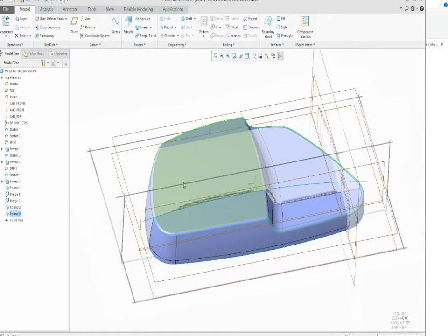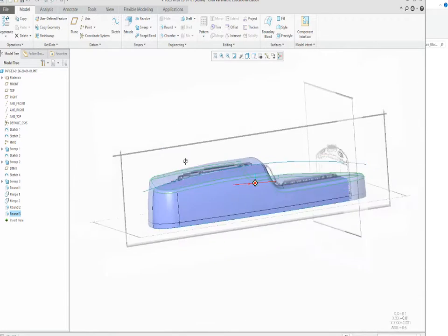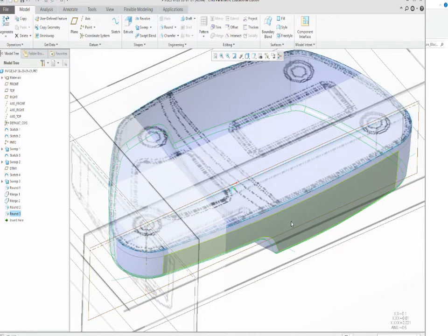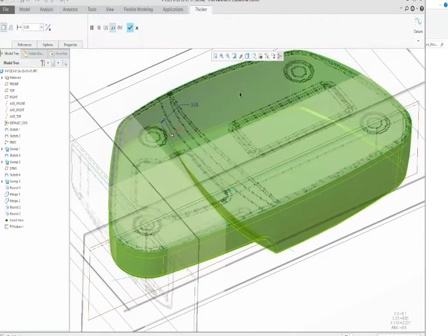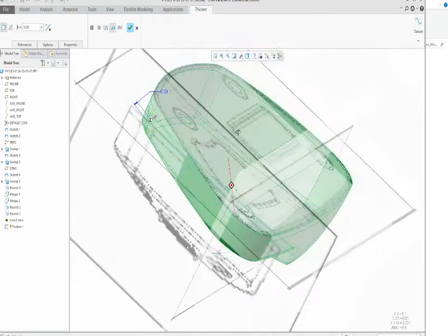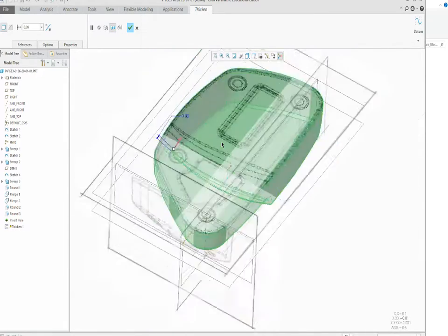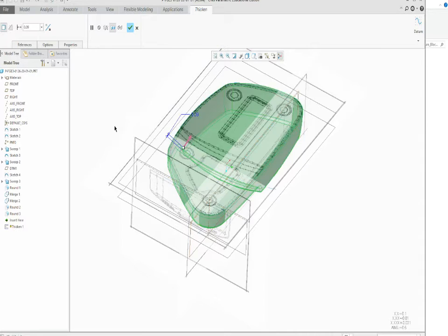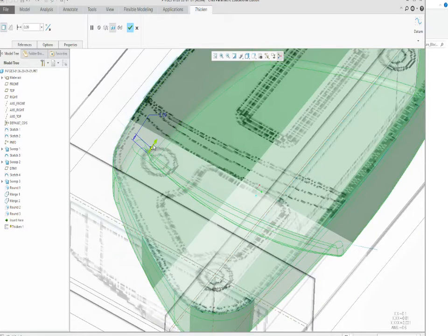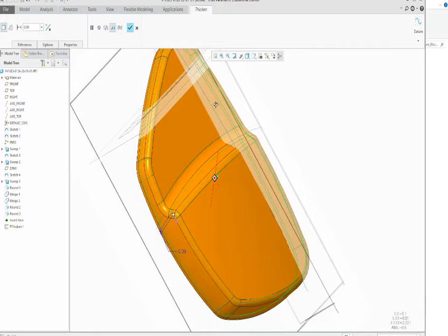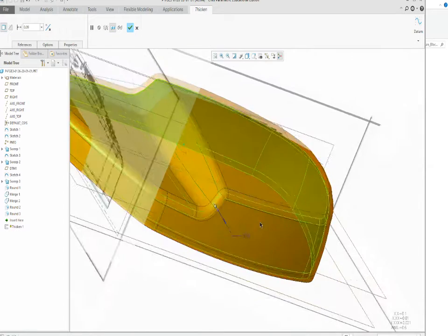And the next thing we need to do is start to thicken the part. Now we're going to jump into solids for the part. So when we touch it, we hit thicken. Thicken is going to have a tendency to tell you the thickness that it can get. And if you're in the solids mode, you can see it by projecting it inward or outward. And that's where you're going to see how big you can make the part.